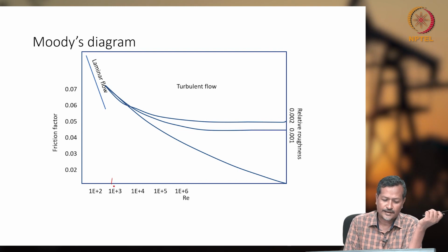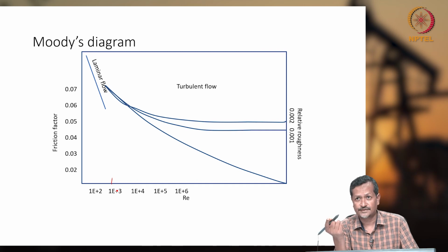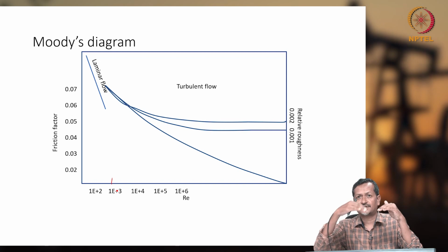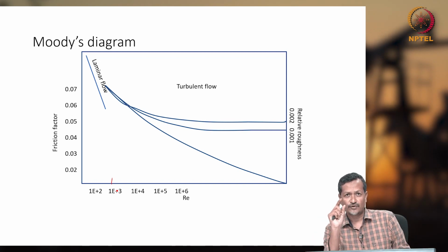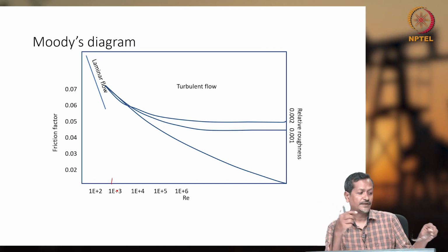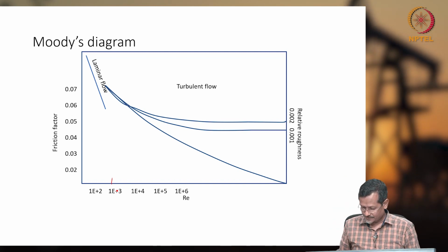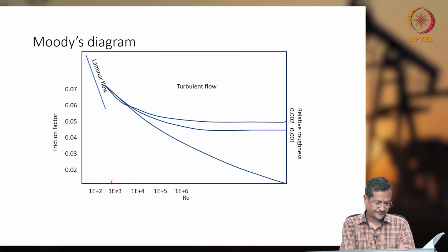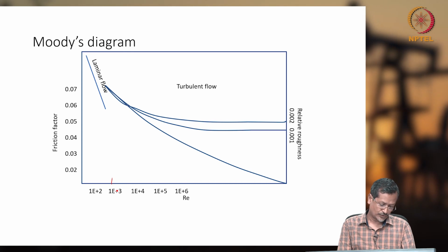Then you have to calculate the pipe roughness or relative roughness value. What is the relative roughness? When you see the pipe is very rough or has small roughness, that exact value of roughness divided by pipe diameter will give the relative roughness. Sometimes we give the relative roughness value in the problem. In that case the value is given as 0.001.